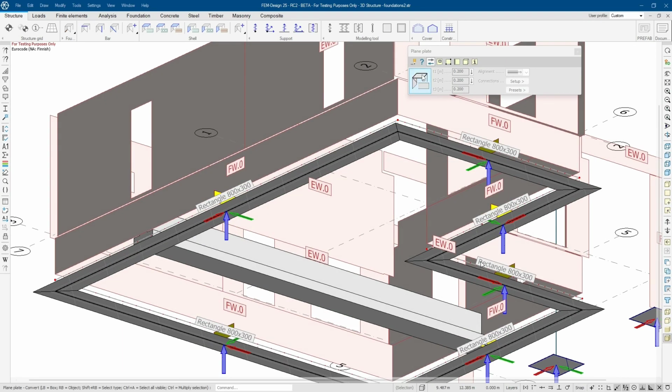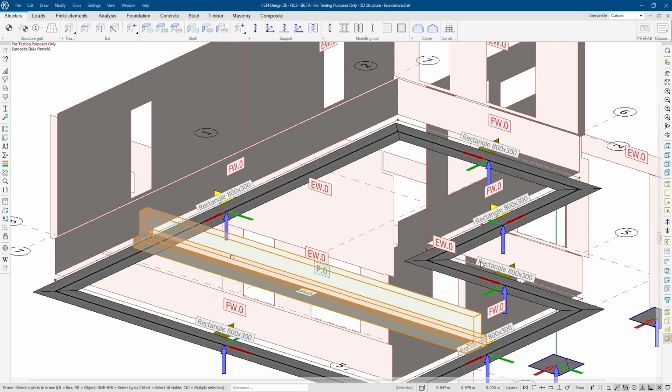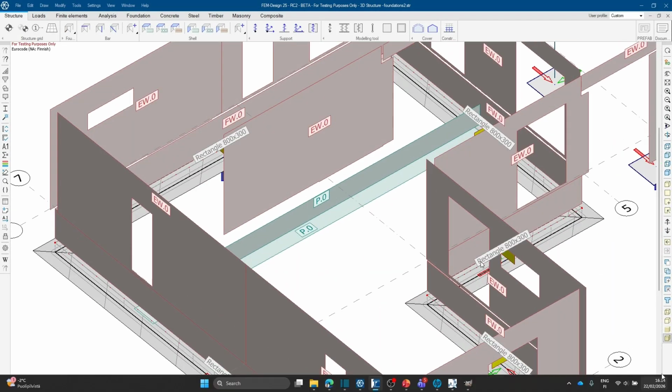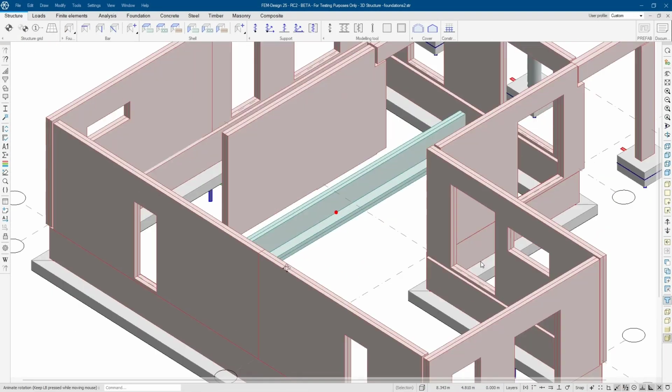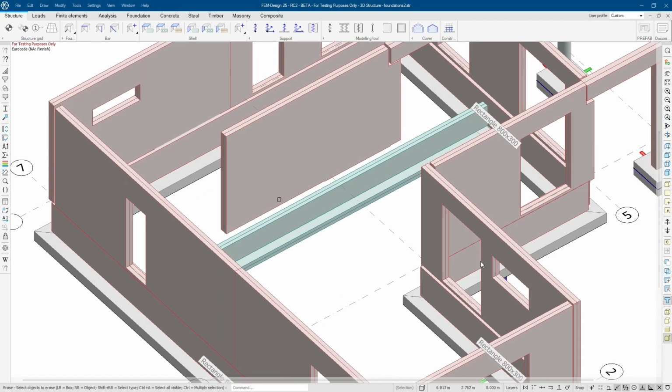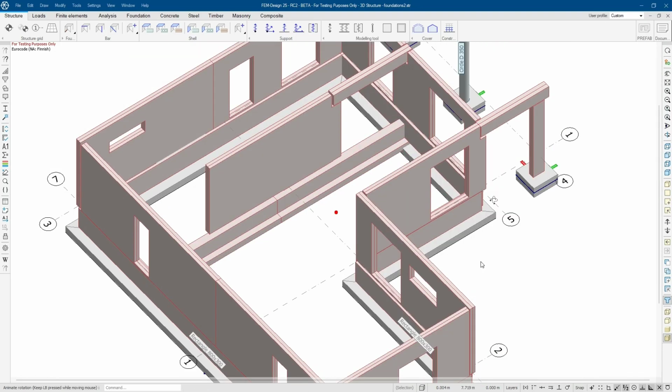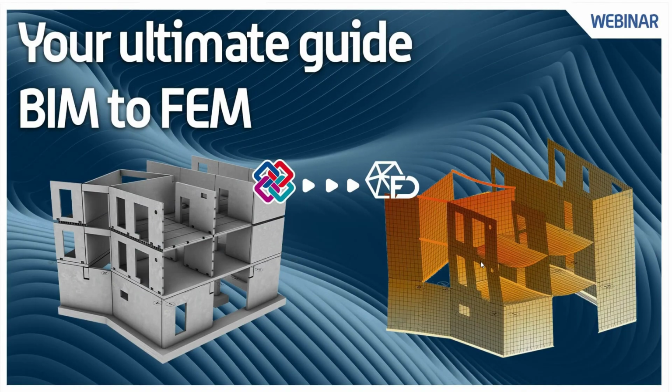So for instance, this foundation bottom plate you can probably generate from the bottom surface of the foundation, because now it's the right size. And this base wall we can also generate from the side of the solid, and then we can align those objects together later. And now we have exactly the data model that we want in the finite element analysis. Just align the objects together and connect them, and then you are done. I don't want to go too deeply into details, so if you are interested in how to do those alignments of objects and correction of floating point issues and out of plane issues, I held a webinar, so it's somewhere on YouTube if you want to find it.